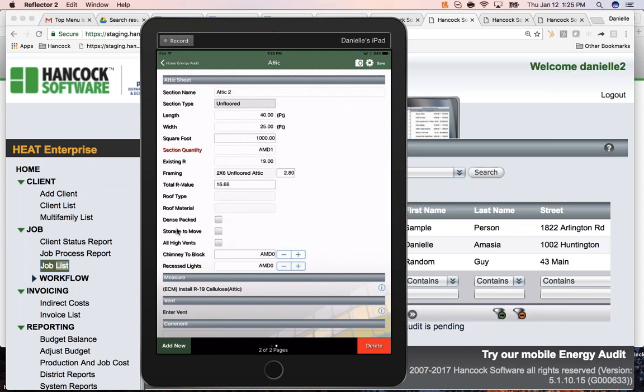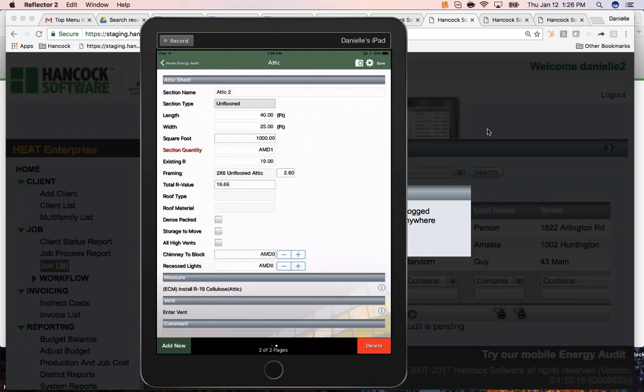Then for single family, you're going to see other inputs that aren't actually energy modeling. But for manufactured home, these inputs come into play in the energy modeling. Is that correct, Art? Yes. So for now, we're not going to go into the details, but roof type and roof material do not have an impact on single family home energy modeling, but they do on manufactured home energy modeling. Yes, it will, simply because of the smaller volume in the attic, we have to calculate a space temperature.